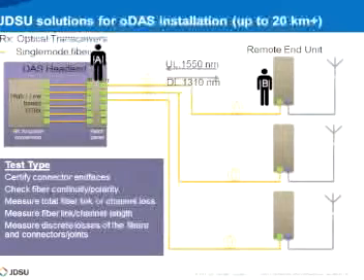So these are just examples of some of the tests that we recommend in different applications. This is the outdoor DAS. Due to the different configurations, they use one fiber. They use the 1515, 1310 as upstream and downstream wavelength. And the length of the fiber is over 20 kilometers. There are probably more spikes in those and more connections. The recommendation is, besides the interface inspection and checking that the right fiber is connected to the right link, an OTDR test.